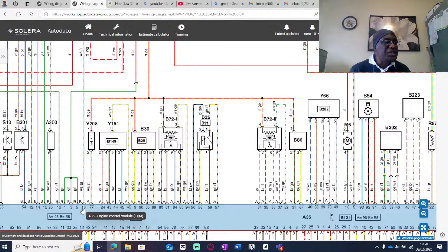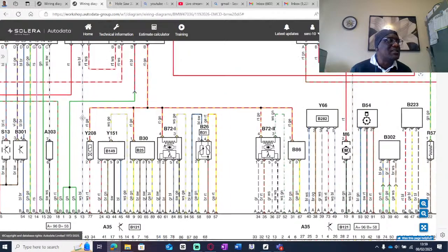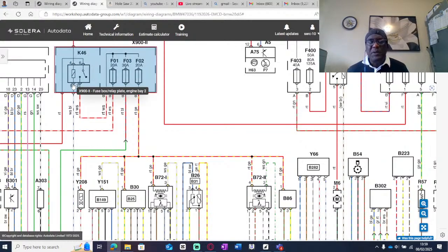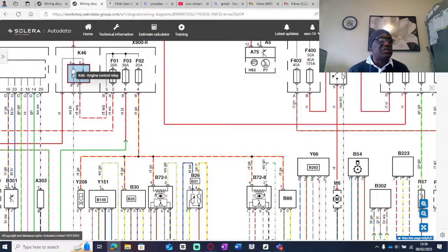The ECU switches ground, supplies ground here. So now the coil has got power and ground. It becomes the load that I always tell you about. I'll sing that to your ears until it makes sense. Now we have voltage being consumed here because we have a complete circuit, now that we've got a power and a ground.